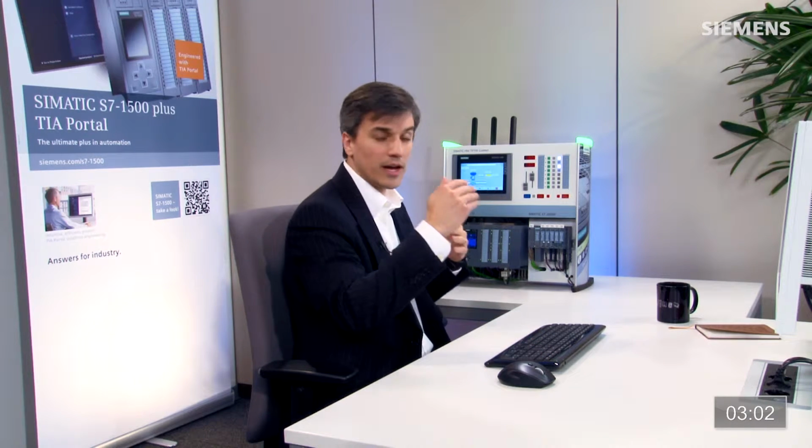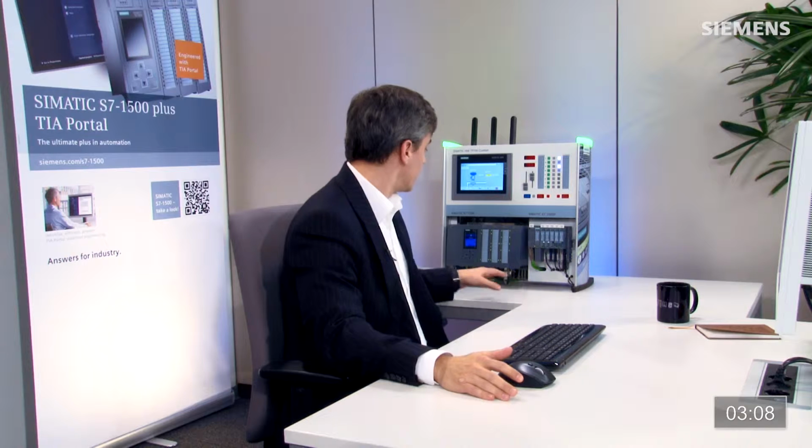Okay, so that's our standard automation architecture from an HMI standpoint of user administration, who has rights to do what. What's new? We have a display on the 1500 and you have the ability to change the IP address. So can we lock that down? Well, of course we can. Let me show you how I do this.